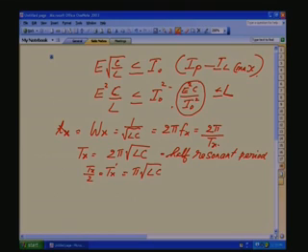Okay, and we want this half resonant period pi root LC to be much smaller than the T off minimum required. So, to ensure this we will say 10%. So, these are all design criteria, 10% of the duty cycle, minimum duty cycle.